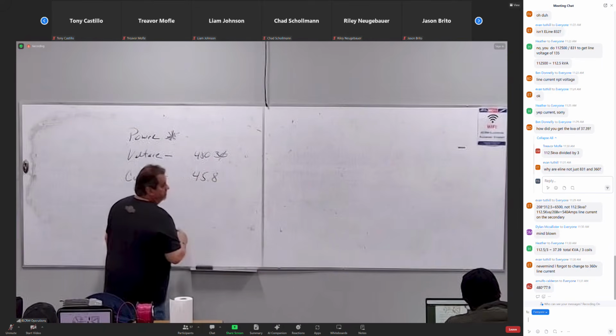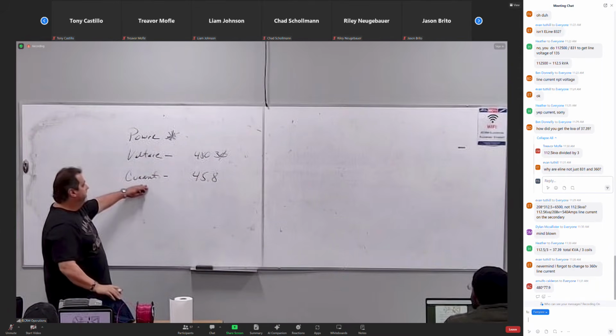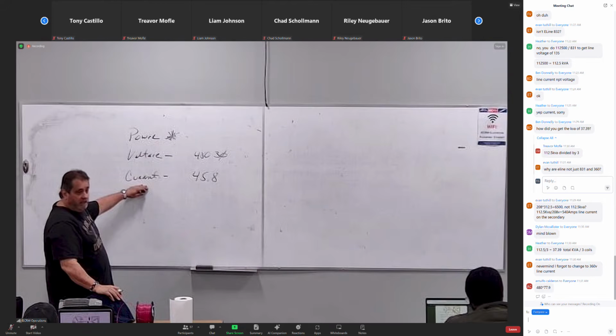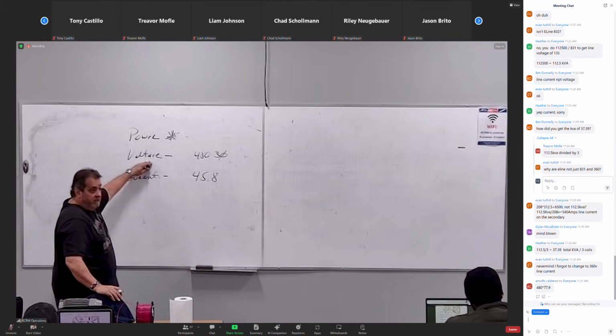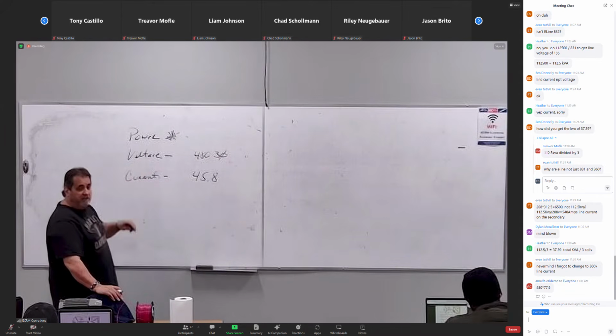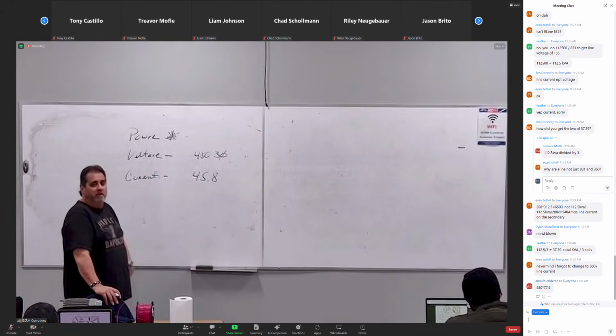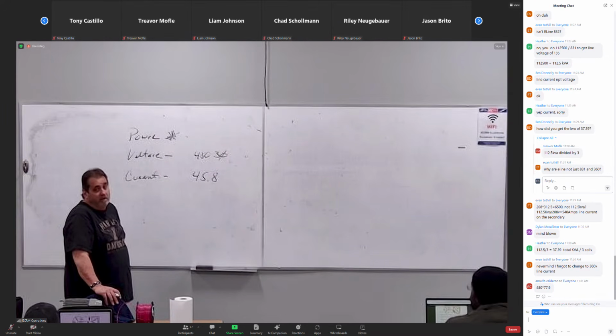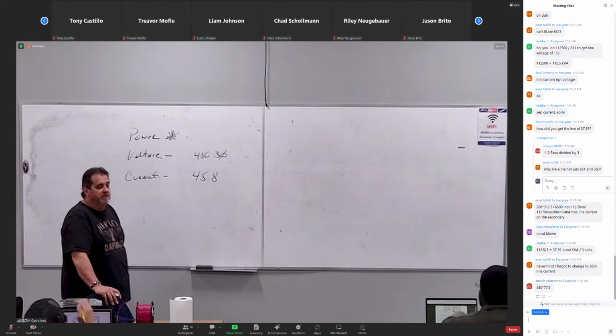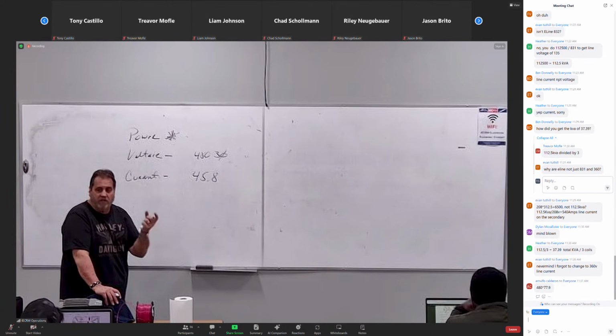Let me ask you a question. I line goes with what? E line, right? Especially on my load. What's my load? A delta. Line current isn't the same as coil current in my delta. But this question asks where amp probe 3 is. Where is amp probe 3? It's on the line. They're asking for line values.